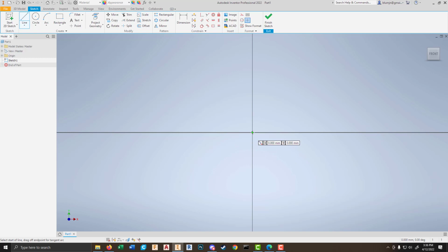So I know that I am going to need a line that I'm going to orbit about, right? This is going to be my axis. This is the center of my propeller. And then offset from this a certain distance, which we will add the distance later, we're going to have our inner spiral, right? And so our inner spiral is going to start down here at this green point that I'm hovering over. And it's going to be offset by a distance of this line. And we're going to deal with that right now.